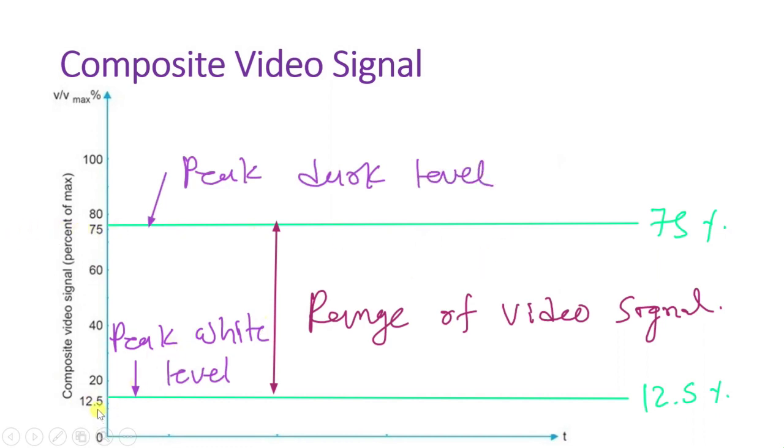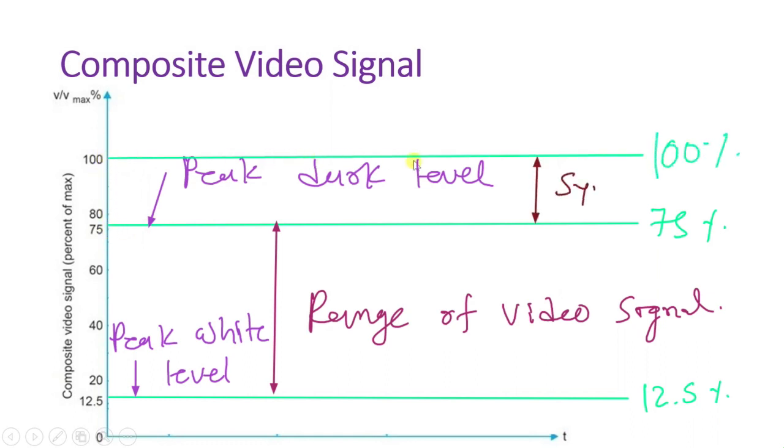7.2 IRE scale of video signal amplitude on an oscilloscope monitor. The amplitude of the video signal is usually checked along with negative sync polarity to conform to the IRE scale shown in Figure 7.5. IRE is an abbreviation for Institute of Radio Engineers, which is now called IEEE, Institute of Electrical and Electronic Engineers. The total IRE scale includes 140 units with 100 increasing and 40 decreasing from 0. The peak-to-peak composite video signal includes 140 IRE units.